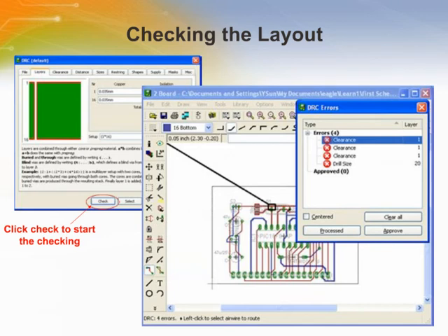If the Design Rule Check finds errors, an error window opens automatically. It lists all the errors found. The window can be opened at any time by means of the Errors command. Each error is marked with an error polygon. Its size tells you, for example, in the case of a clearance error, about how much the limit is exceeded. If an error in the list is selected, a line points to the corresponding location on the board.